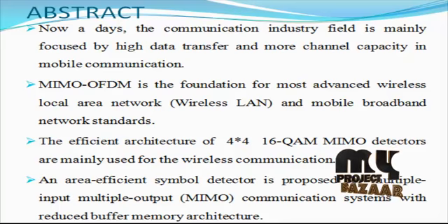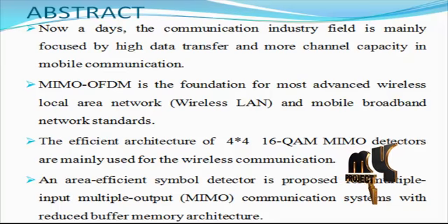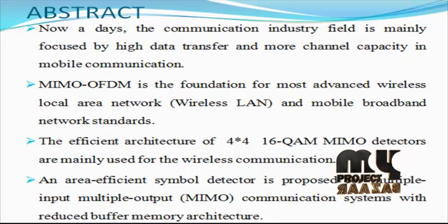Its main advantage is to provide a lower peak-to-average power ratio, which makes the technology the choice for the uplink. However, the implementation of the MIMO detector in the SC-FDMA system is significantly more complicated than in the OFDMA system. This is due to the fact that the transmitted data is mixed together because of the extra DFT block used in the SC-FDMA system.